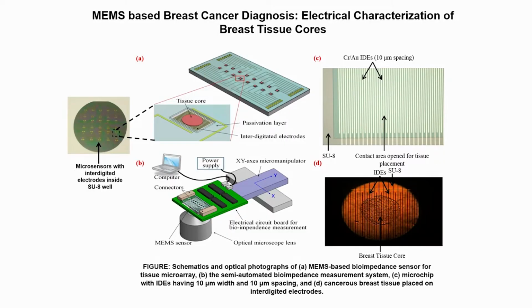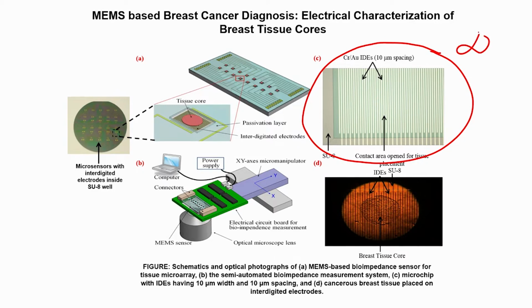these are the interdigitated electrodes here, okay, and what will be the impedance of this? Impedance of this would be infinite or extremely high. Why? Because there is nothing on these interdigital electrodes, and there are only metal lines not connecting with each other, right.